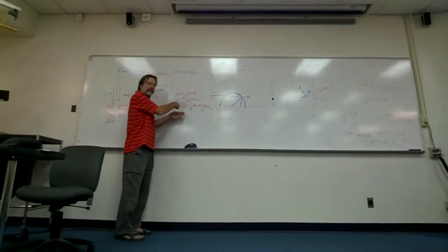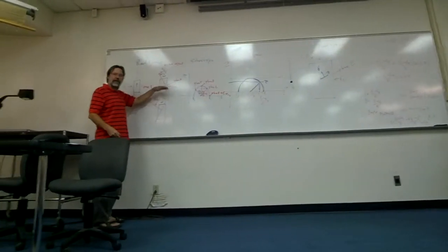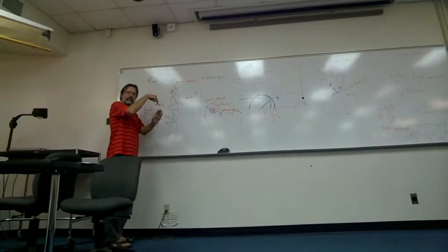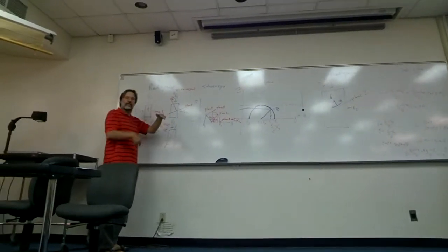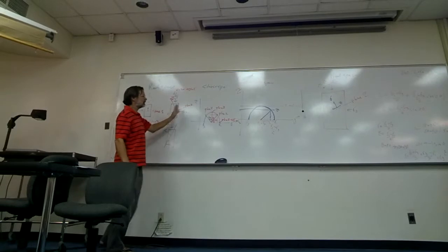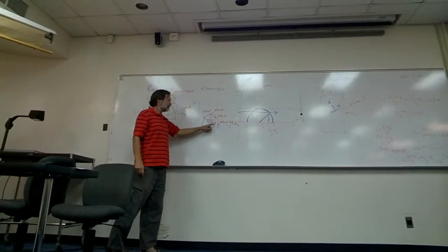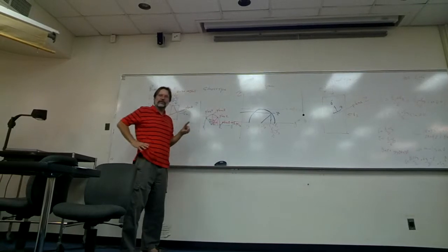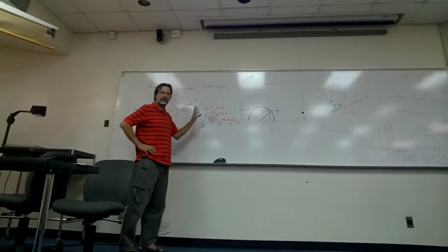The point of this is that what that circle shows is the variation of the resolved shear stress and normal stress for different planes relative to that experiment. So once you know the magnitude of sigma 1 and sigma 2, you always know what the stresses were on any plane.